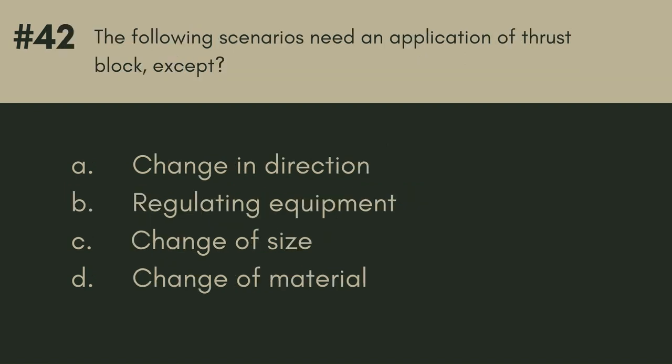Question 42. The following scenarios need an application of thrust block, except A. Change in direction. B. Regulating equipment. C. Change of size. D. Change of material. The answer? It's D. Change of material.